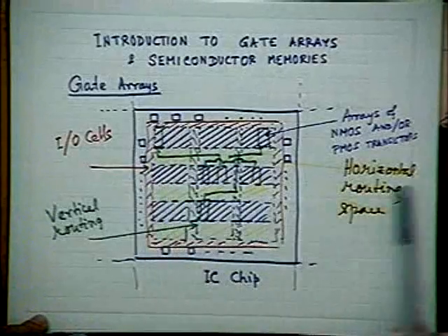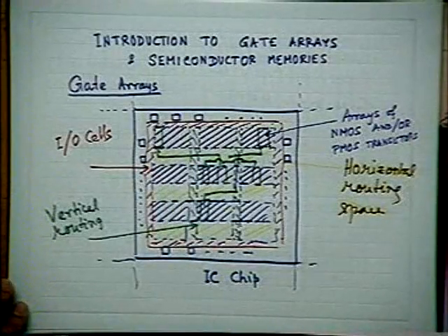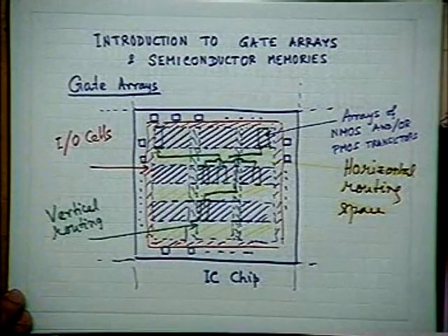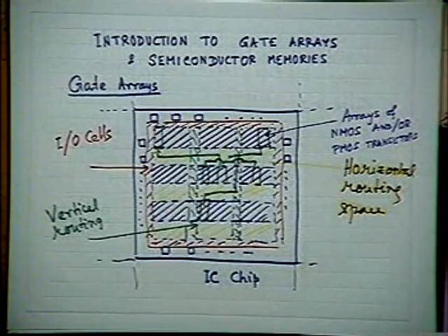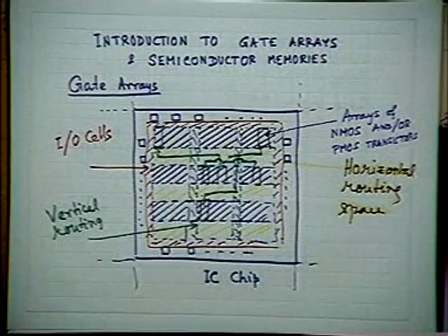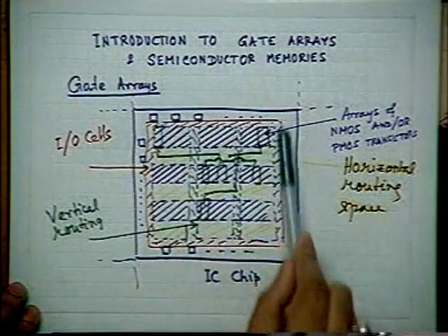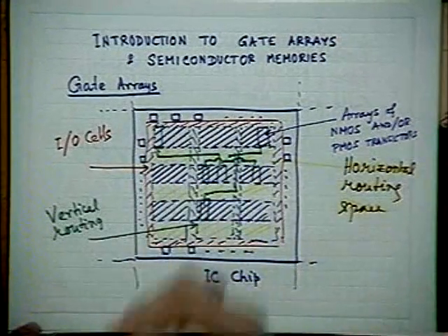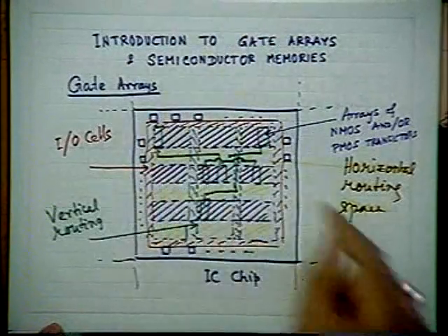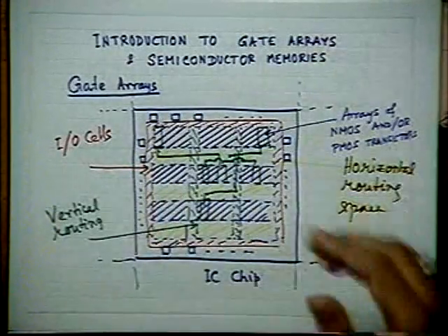But on the other hand, input-output, maybe depends on the signal level. You may have to amplify, you have to enhance the power of the input signal. You may have to deliver more power at the output for buffering. Therefore, input-output cells are not gate arrays. They are fixed amplifiers or gates, inverters, okay, with appropriate power delay products, and these are located at the various locations, and we have to connect them via again the routing space to perform your function.